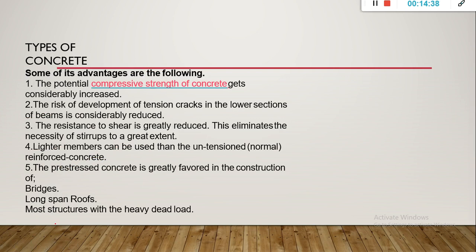Pre-stressed concrete has many advantages. The potential compressive strength of concrete is considerably increased, the risk of development of tensile cracks in the lower section of the beam is considerably reduced, the resistance to shear is greatly increased, and lighter members can be used than in untensioned reinforced concrete. Pre-stressed concrete is greatly favored in construction of bridges, long span roads and heavy structures. So it has many uses.